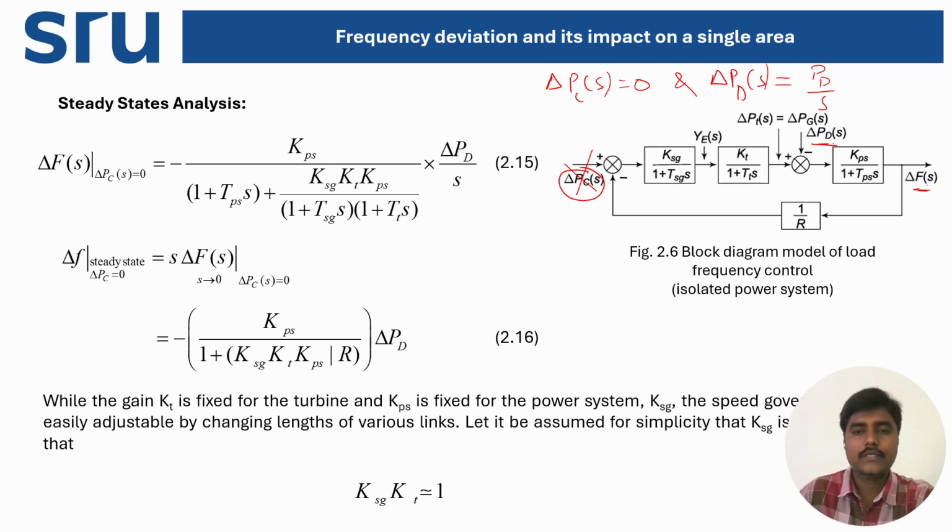For this case, you can derive the transfer function by using block diagram reduction rules. The transfer function can be defined as the ratio of the Laplace transformation of output divided by the Laplace transformation of input. Here delta F of S is the output.